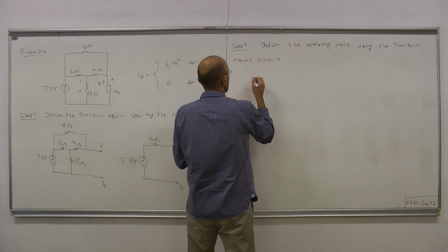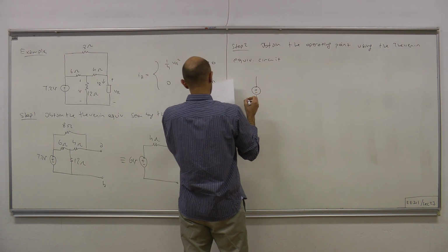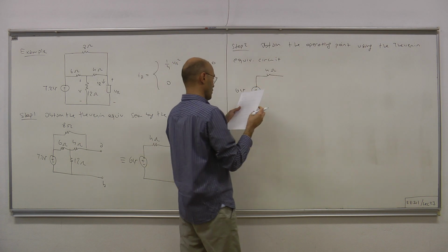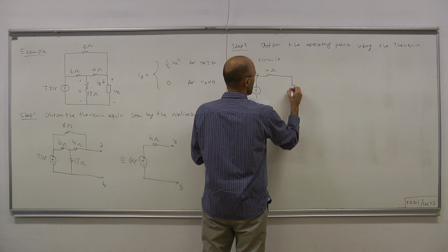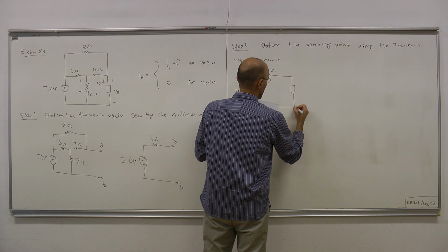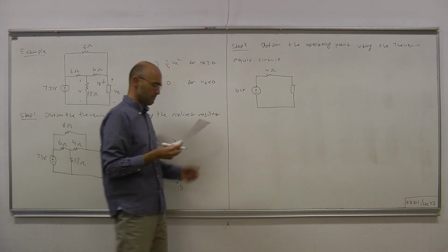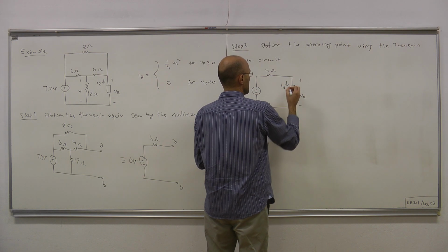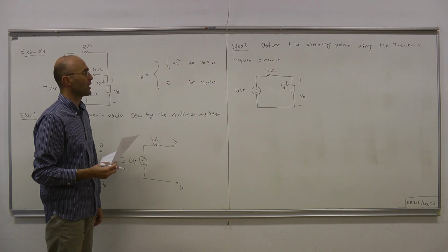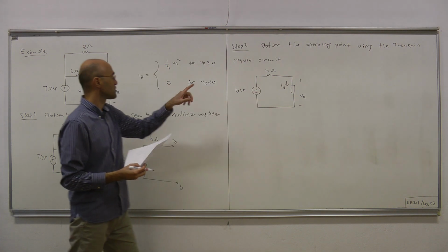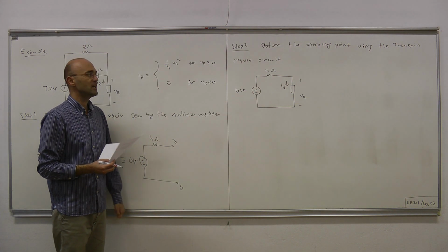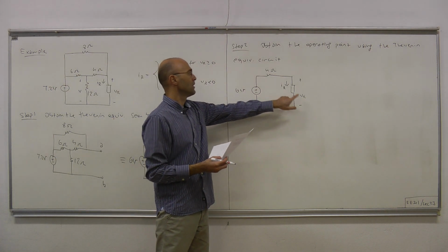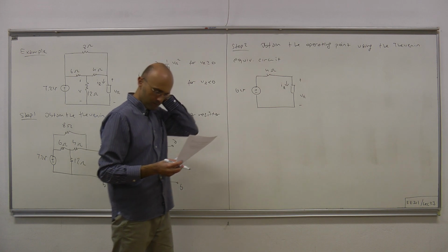Okay, so this is the Thevenin circuit, 6 volts, 4 ohms, and we have the nonlinear resistor, plus minus VR, and here is the current IR. Using this circuit plus the thermal equation given for the nonlinear component, we will now figure out the operating point, IR and VR.